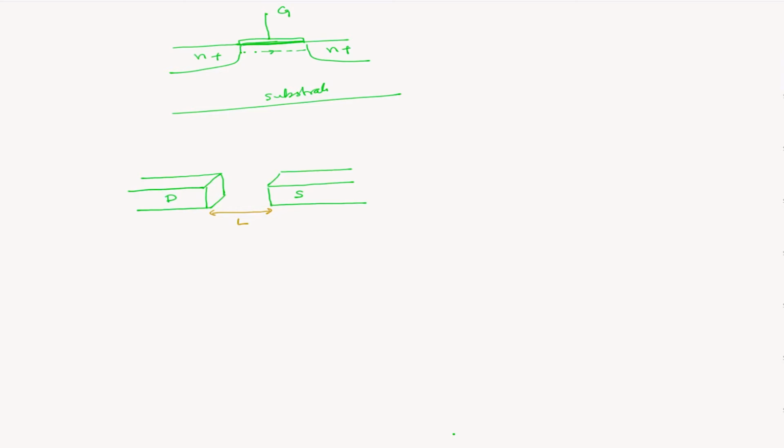It's 14 nanometers, it's a 14 nanometer technology. 10 nanometers is a 10 nanometer technology in simple forms. In an actual transistor, when you go deep, your effective length can be a little different than this length. But anyway, for simplicity, let's keep it like that. So this length is the technology node we talk about. And the other one, this side, this distance is the width of the transistor.